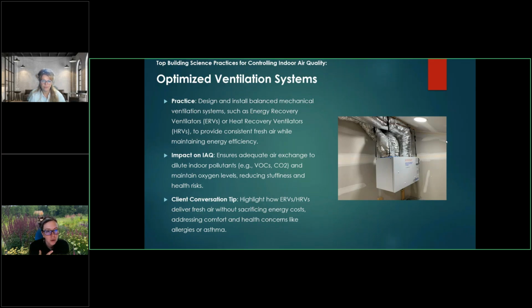So many things are so important about ventilation being in the places that you want it to be and to be balanced, which I'm not sure if we have a slide on here, but having somebody check to make sure that none of those ducts are kinked and you're actually getting the ventilation, either exhaust or supply, to where you want it to be is critically important. And I think balanced is an interesting conversation to have, because what balanced ventilation means is that the ductwork is balanced. The air, those fans going in and out, is balanced. It's not that the house is balanced.